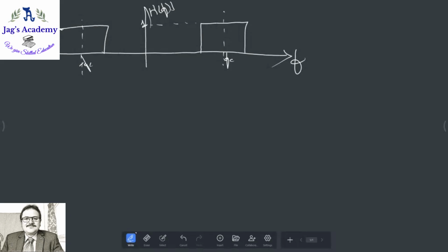Right, okay. Now, while filtering in the frequency domain, we simply multiply, right? We simply multiply, yes or no? Now, see here, this is your B, this is your B, okay? This is a band pass filter with the center frequency Fc and with the bandwidth of 2B, right?